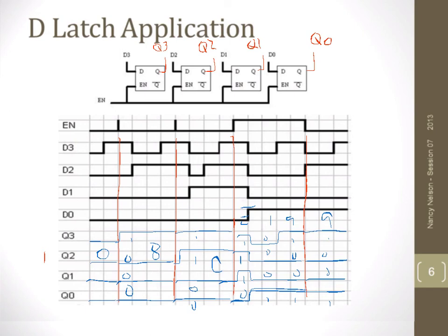So this shows us very simply that with a D-latch, we can take spontaneous samples or instantaneous samples, or we can enable them to watch a data stream flow through the device. So as we move forward, we'll see that combinations of latches together are providing us with some fairly useful devices.